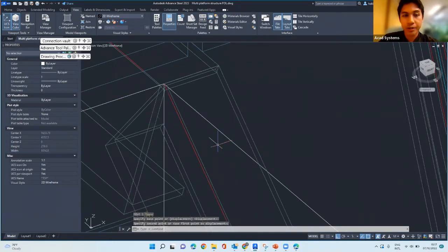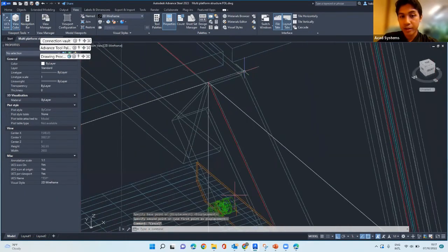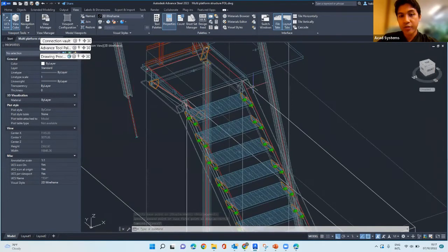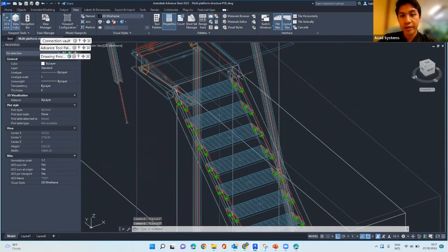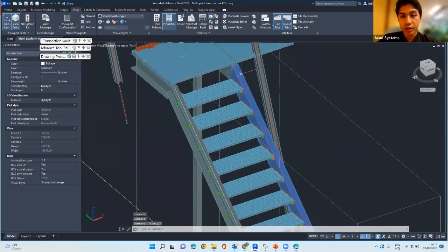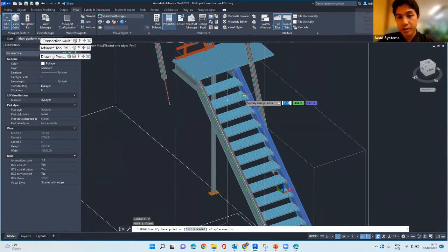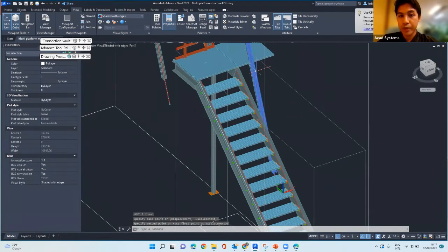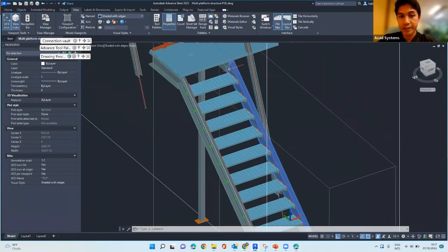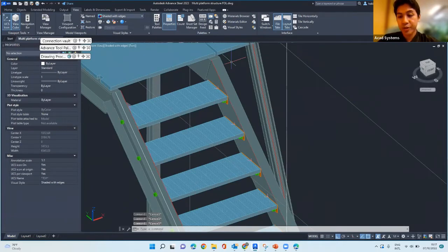Okay, it loads a little bit. Then it moves to that position. If you try to move it directly, you won't be able to move it. For example, I'll change this back to shaded. Let's say I select this, then M space, bring it here, click, and it will not move. It will bounce back to the original place. So you just change to wireframe and then move it.